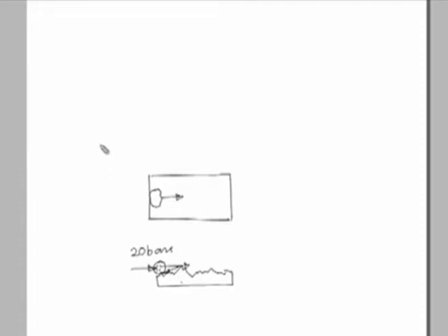This can be also seen in this way. If this is the workpiece, in which this is the abrasive particle which is flowing through this surface, and the surface contains some asperities like this, then these abrasive particles, as we have seen in the last session also, will either remove these peaks on its way while pushed in the form of media under some pressure, something like 20 bars or so.